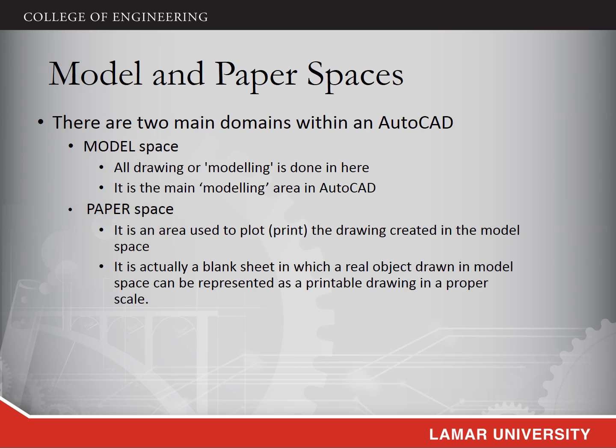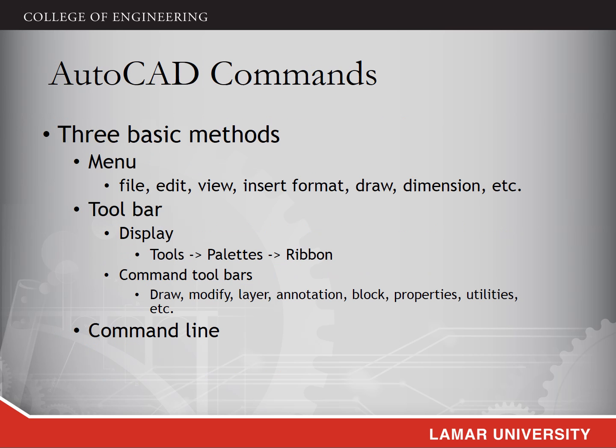These two spaces are very different. We should know that all the objects in the model space are the actual size. The scale is always 1:1, but in the paper space, we can set any standard scale for the objects.